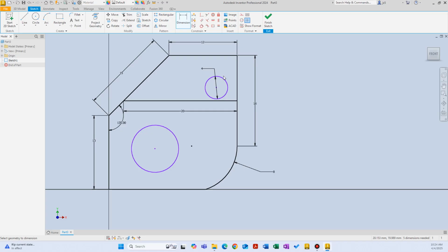I just clicked on the circle and assigned the diameter for that circle, but it is still not fully defined because right now I just right clicked and clicked OK to get out of that command. Right now I can't make the circle larger or smaller, but I can move it around by holding the origin point of the circle.